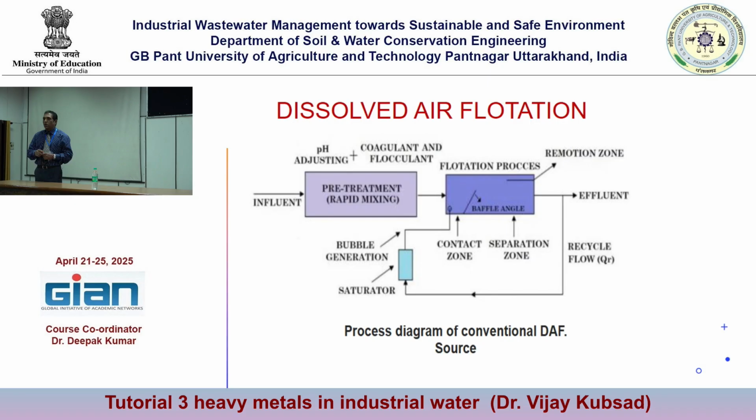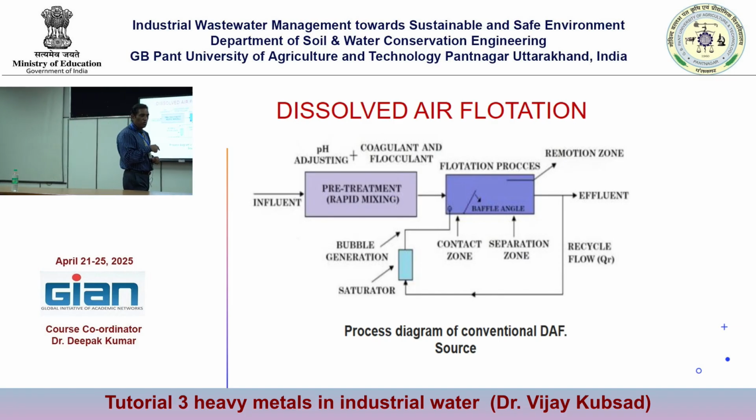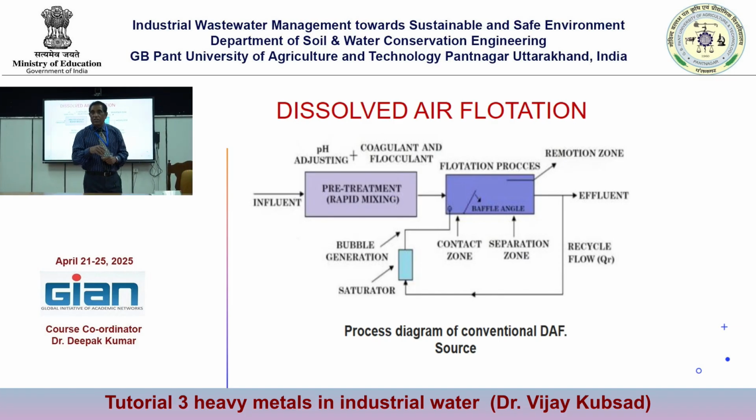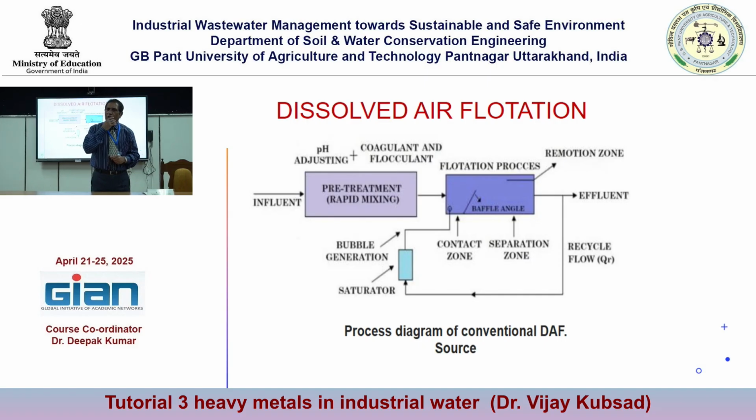You have the right to require them to reduce the suspended solids and then discharge. Otherwise, everything will be disturbed. If one industry is doing like that, what will you do? You will build big primary settling tanks, and then the BOD is also high. If the receiving industrial wastewater treatment plant is not capable of taking that BOD, you cannot put in a high BOD anytime. They said that we can handle only this much. The rest you will have to treat.